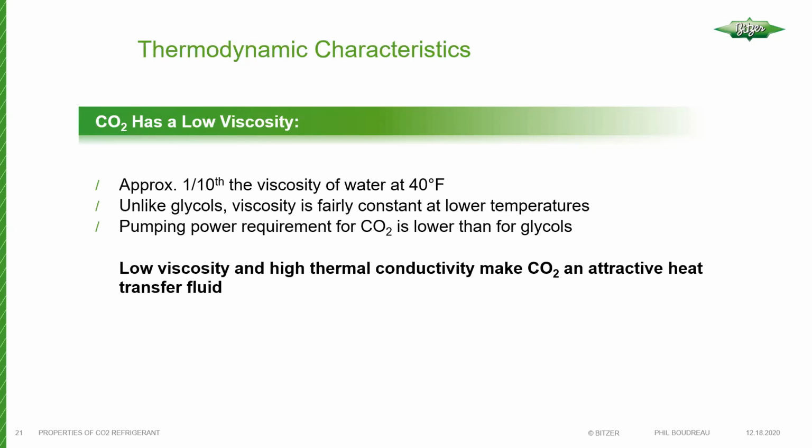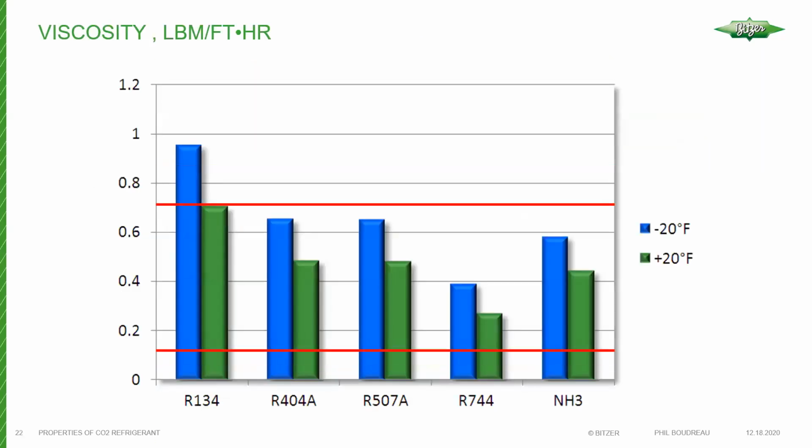Due to the low viscosity, the pumping power requirement for CO2 is lower than for glycols. So CO2 is actually used as a heat transfer fluid, not necessarily in pressurized equipment, but also just to be pumped around and extract heat from a heat source. So the low viscosity and the high thermal conductivity make CO2 an attractive heat transfer fluid also.